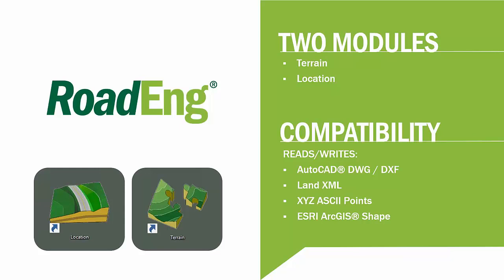It is the survey map module where you can enter in P-line data. The other two modules I will focus on today, the terrain module where you can import total station data, GPS data, LiDAR data. So there's a whole bunch of different forms of data that you could use. Today I will focus on total station data, but you can use any types of three-dimensional data. You import that data into the terrain module, and then in the location design module you design your road or your alignment.